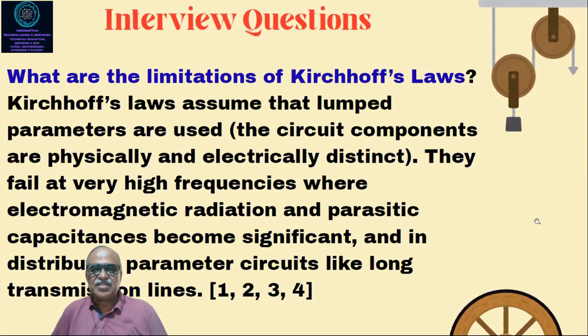So what is the limitation of Kirchhoff's law? This is very important. They may also ask you about the limitation in the questions, so you should be prepared. Kirchhoff's law assumes that lumped parameters are used. What are lumped parameters? The circuit components are physically and electrically distinct.